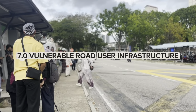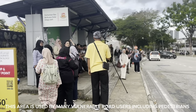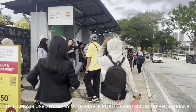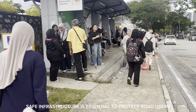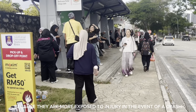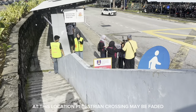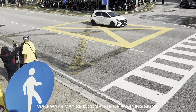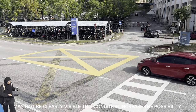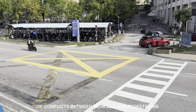Vulnerable road user infrastructure. This area is used by many vulnerable road users, including pedestrians, cyclists, and motorcyclists. Safe infrastructure is essential to protect these road users because they are more exposed to injury in the event of a crash. At this location, pedestrian crossings may be faded, walkways may be incomplete, or warning signs may not be clearly visible. These conditions increase the possibility of conflicts between vehicles and pedestrians.